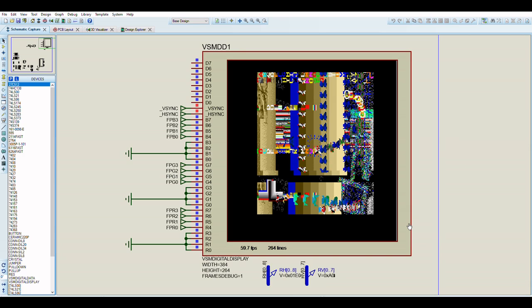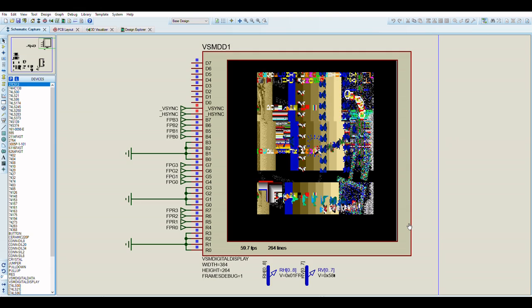The original BombJack arcade hardware did have quite a lot of features. It would automatically do sprite multiplexing if you updated the hardware registers at the right time. It's just that you would see RAM contention issues because you would be updating the sprite registers at the time when it was trying to read them.